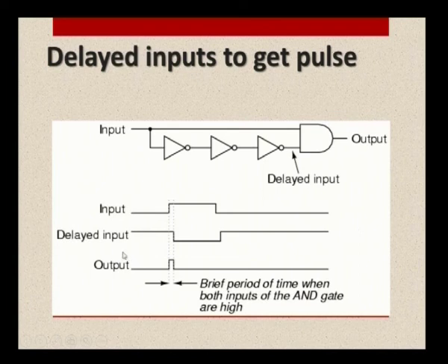Here the x axis represents the time duration. Accordingly it is delayed by a small value, and as an output only when the two inputs are high the output will be high. It is happening only for a small duration here. So, it has produced a pulse. Delayed input devices could also produce digital pulses. We can alter the duty cycle using the digital circuits.